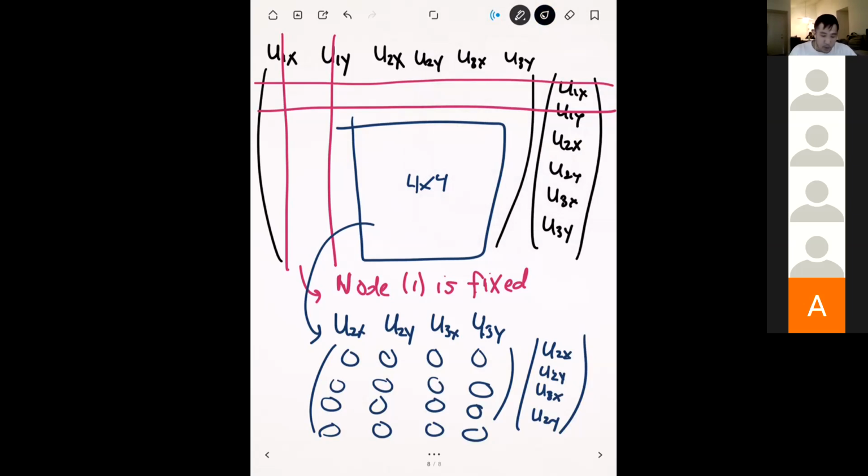And so you're probably wondering, why don't we use this method right here, which results in way less writing and is generally a lot easier to deal with, at least for hand calculations, okay? And the reason you can do this method for these kinds of problems is that whenever we had a Dirichlet boundary condition, the Dirichlet value there was always 0, right? And so that's just kind of the nature of structural problems, where if you constrain a node, then you say that this node cannot move at all. And so the displacements and sometimes the rotations are always going to be 0.